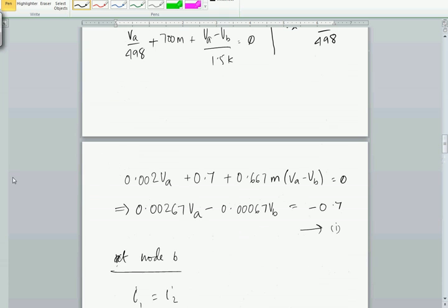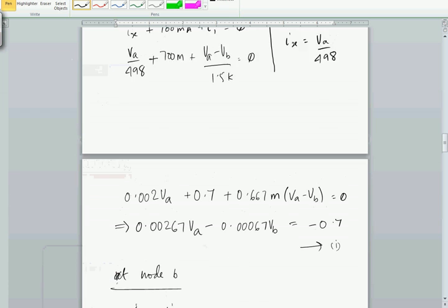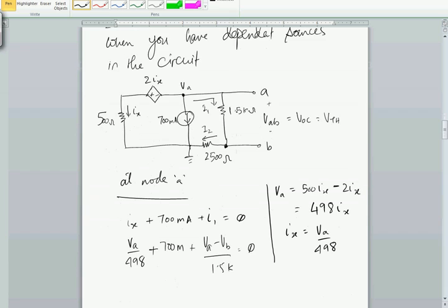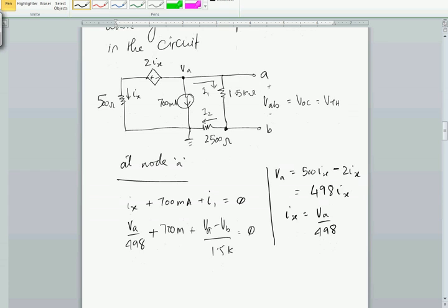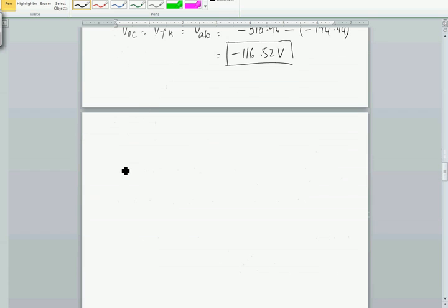Now let's come back to how to find the Thevenin equivalent resistance. To find the Thevenin equivalent resistance, what you have to do is short circuit the terminals where the load was connected, and find the current that is flowing in this short circuit. So that's the first step. We're gonna find the short circuit current. Let me redraw the circuit. So, Thevenin equivalent resistance.